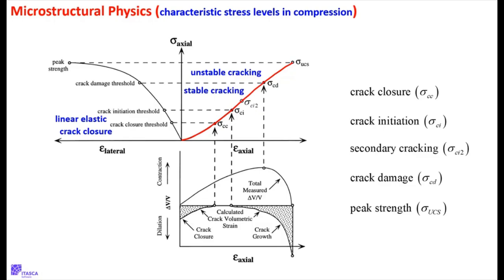There's new surface area forming, and that's subparallel to compression. Because think of it, I squeeze it, and a little crack forms. Boom. Well, that crack now opens a little bit, and it opens in the lateral direction. And if you're super carefully measuring that lateral strain on the surface, you say, oh, it's straining more than it would be if it was elastic. Okay.